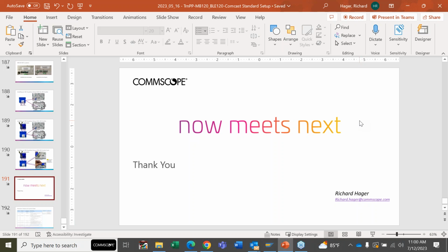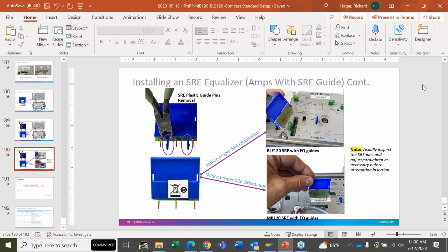So if you put this out in a rural area and you don't have that much voltage, there's a good chance that amplifier might not fire up. There's not much chance that you're going to see this unless you're in mountain areas of Colorado or some rural area. So just make sure you know the model number of the line extender that you have for the power supply.